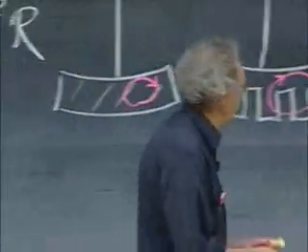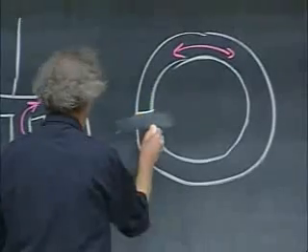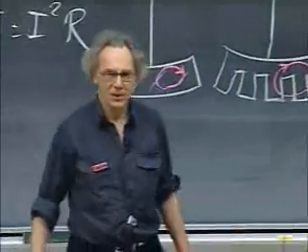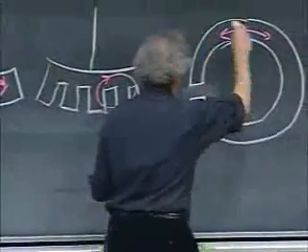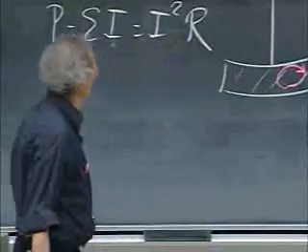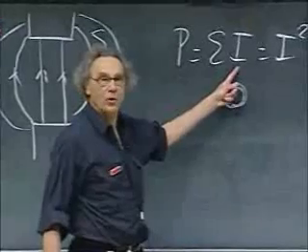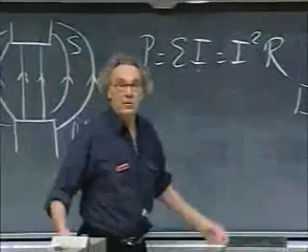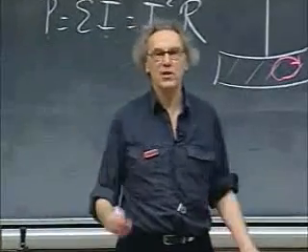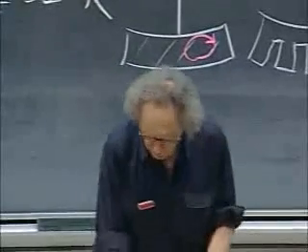And then I will throw through there another ring, which is the same dimension, but this ring has an opening here. Air, the resistance is huge. So the current that is going to flow, this eddy current, is way lower because the resistance is so high. And so there is no power dissipation because I is so low, and so there is no heat produced at the expense of kinetic energy, so there is no damping. There is no strong force that opposes it. And I can show you both.